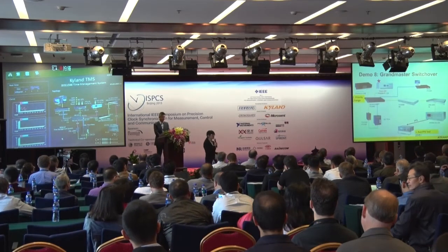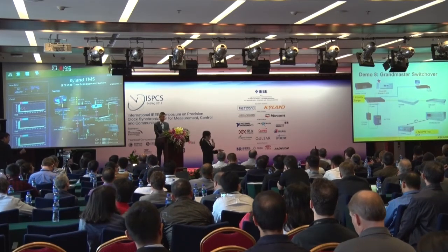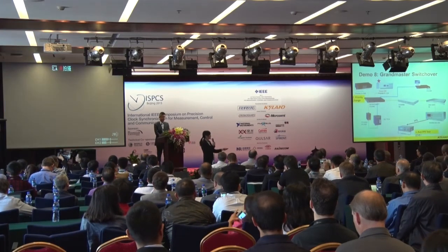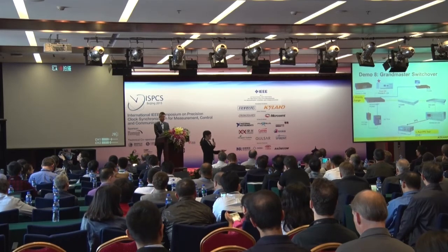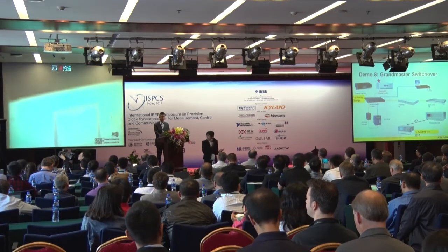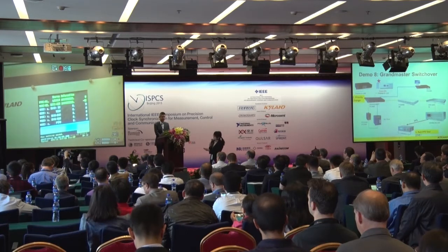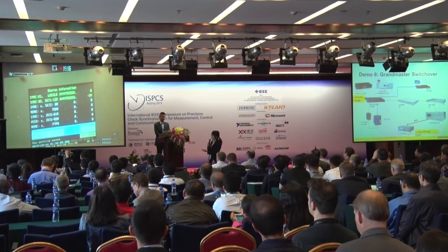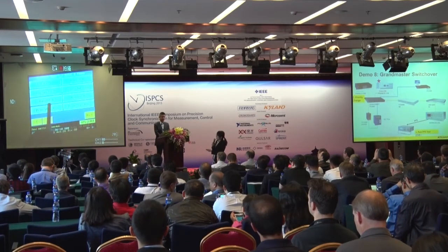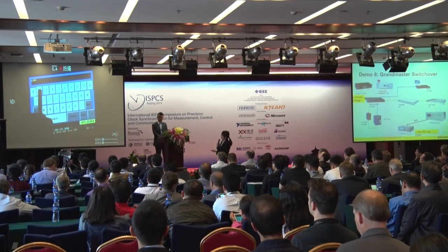So here we're going to do a switch over between different grandmasters. First, we'd like to run the PPS test through the Sifang relay, and we'd like to check the performance during this kind of grandmaster switch over. And then now we change the parameter of priority one in the Kyland clock. We change the priority one from 100 to 200.